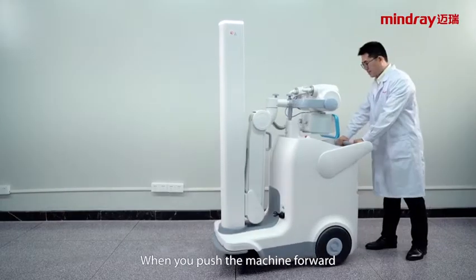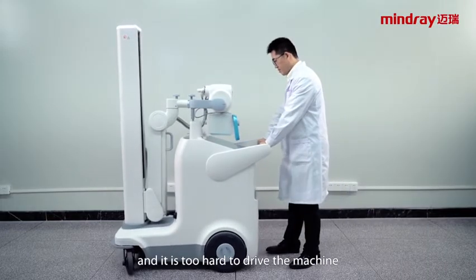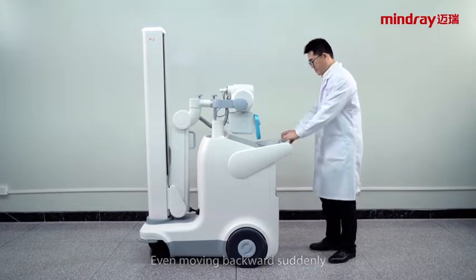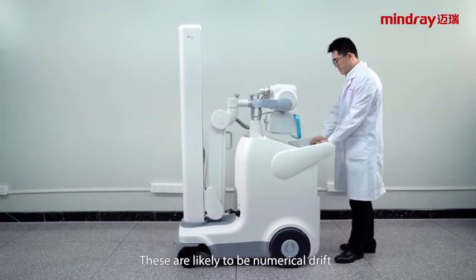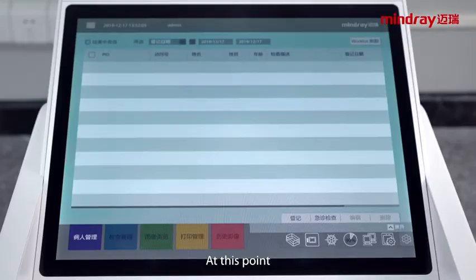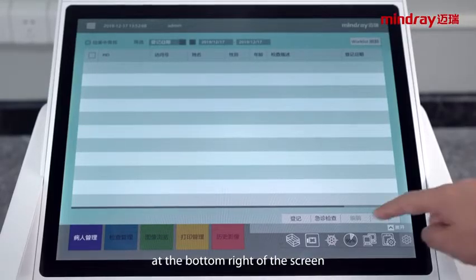When you push the machine forward, the machine does not run in a straight line and is too hard to drive, even moving backwards suddenly. These are likely to be numerical drift or damage to the force sensor. At this point, you can click the machine status icon at the bottom right of the screen.